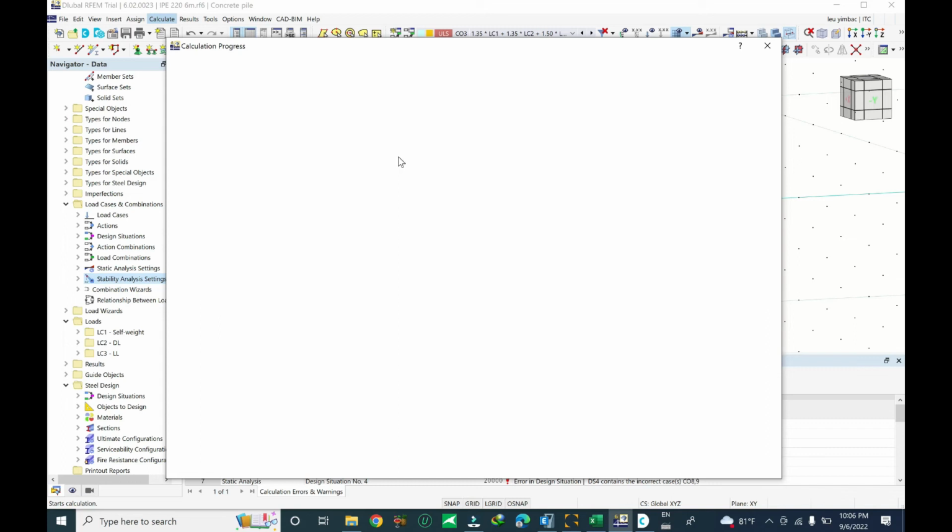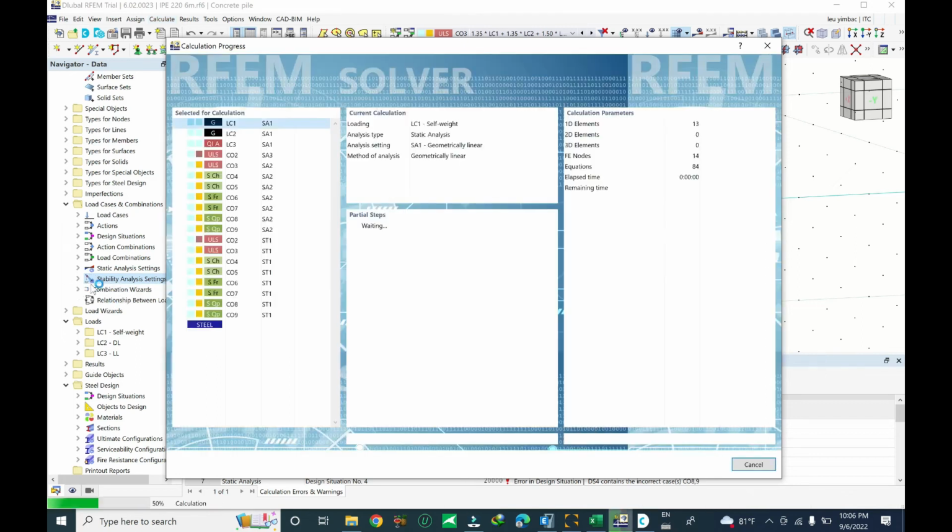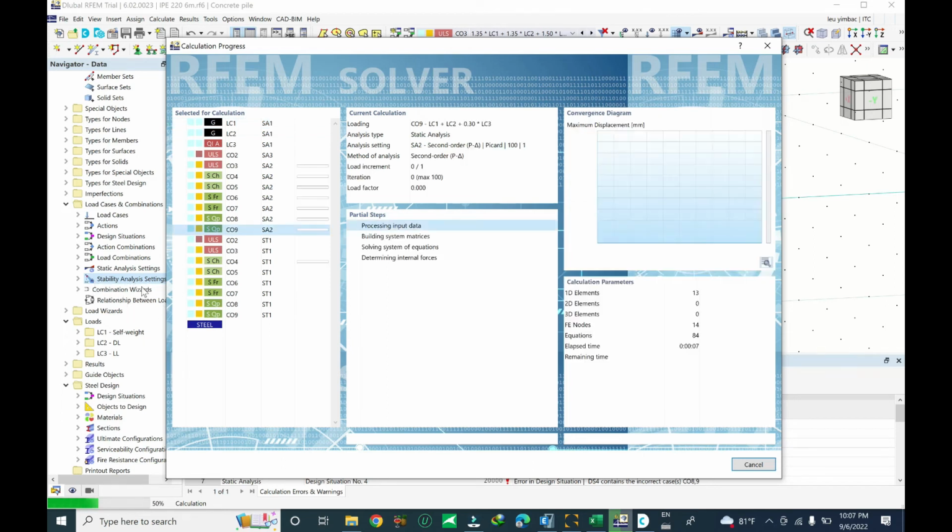Here we check the section, the software does not perform the stability check. Here the capacity is over too much, so the software will alert an error and not perform analysis and design. So we have to change the setting. Let's check it again.